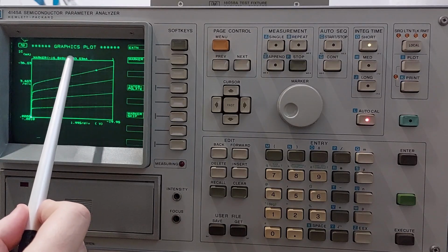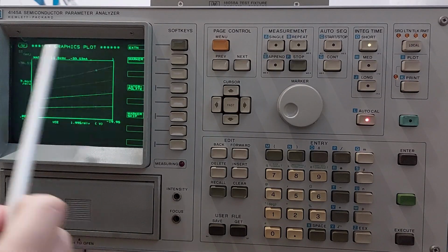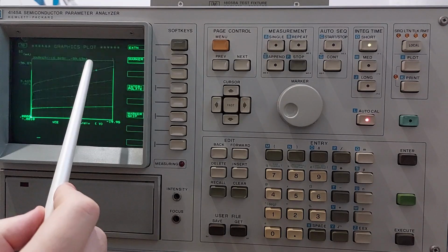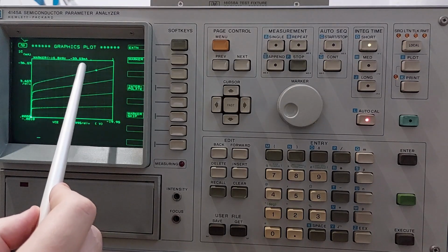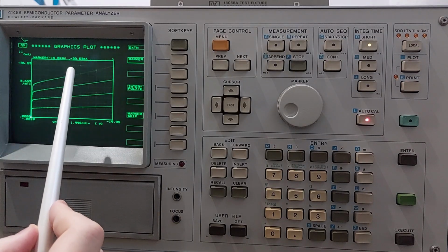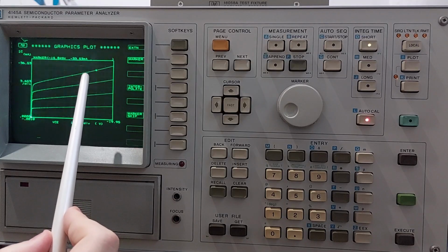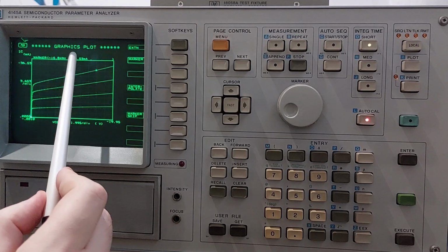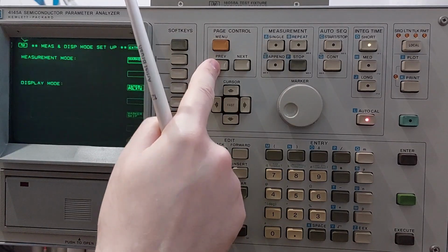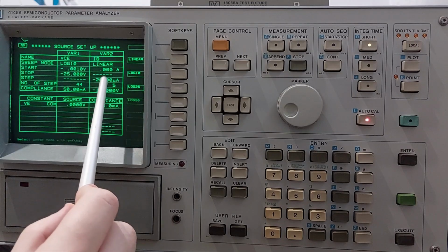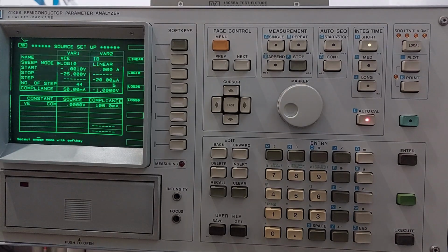So for the minus 33 milliampere collector current and minus 80 microampere base current, we will have roughly the same DC gain value, which is 417. We just divided this one by value of each of these steps, starting from the 0.